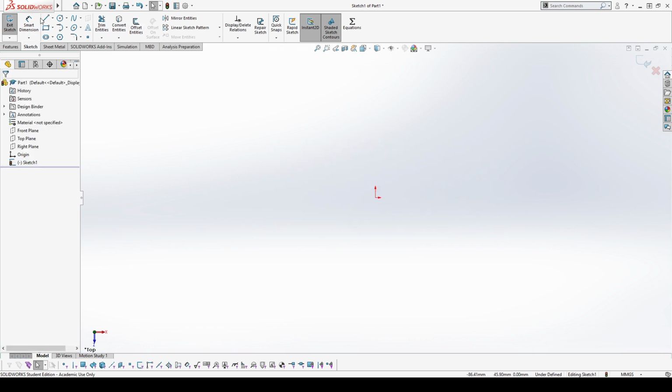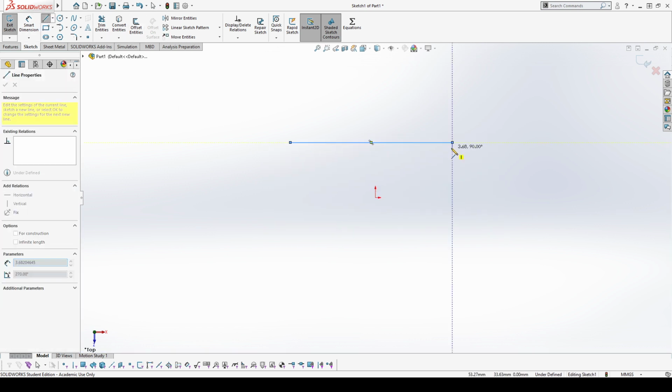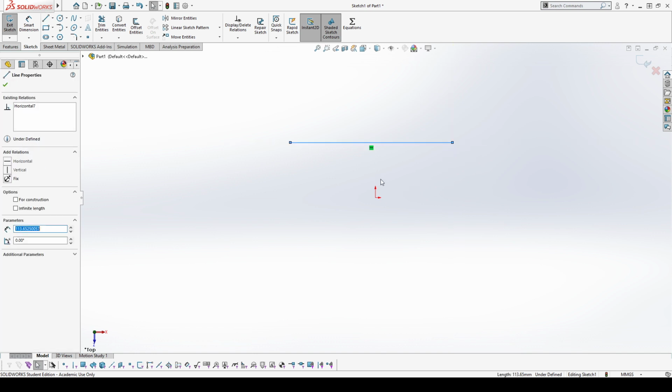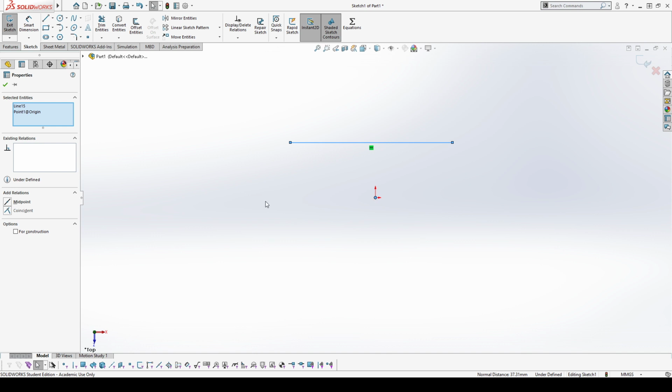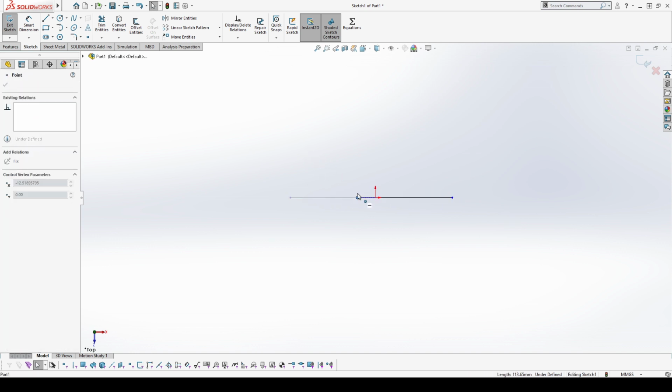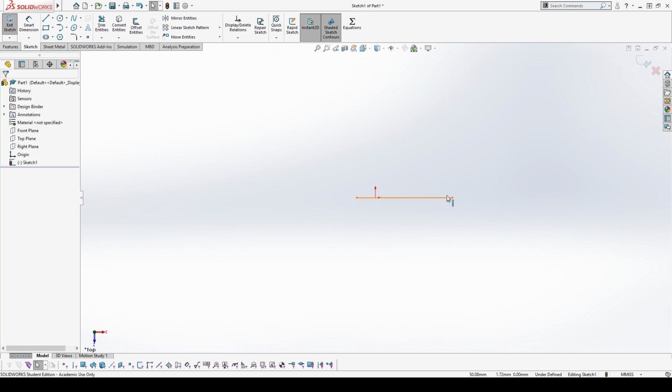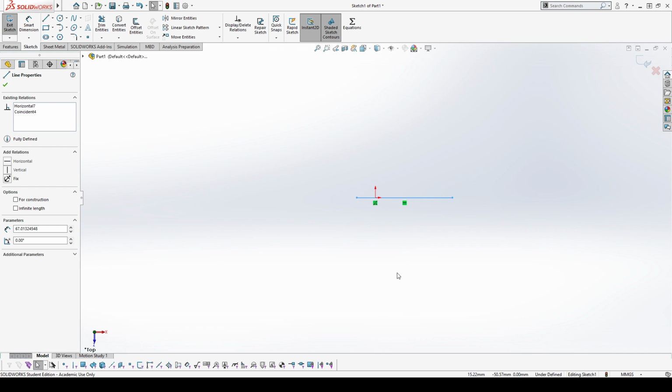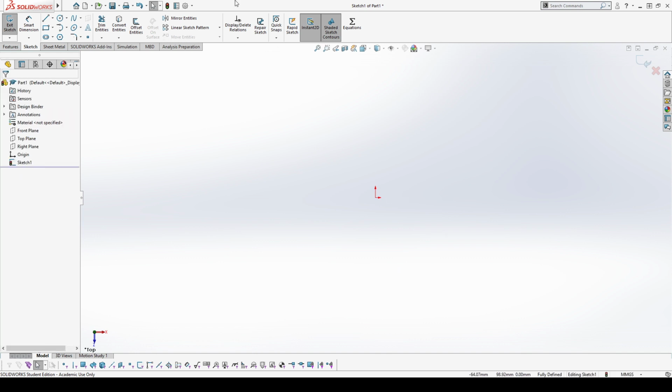I'm just going to go back and create a normal line, just like that. And then I'm going to click that line and then the point that I want to be the midpoint, and then on the left here I can see some relations that pop up. So we haven't seen either of these yet. One of them is a midpoint, so that's what we were talking about. Makes it coincident to that midpoint. The other option that we have is just coincidence. That just means that this line is always going to pass through that point, but it's not going to be symmetrical around it, right? So I can make one side short, other side long, and that gives me those options there. That's really all there is in terms of basic lines, at least for now.